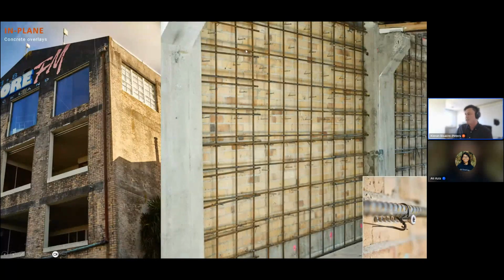One value add that we've managed to be involved in this space is actually the use of mechanical anchors rather than epoxied in dowels as the starters in between the two substrates. Interestingly, chatting to a contractor a little while ago, we learnt that the cost of the installation of the reinforcing and the reinforcing itself is about 3 times the cost of the concrete. And so that's the key driver of the cost on these retrofits.